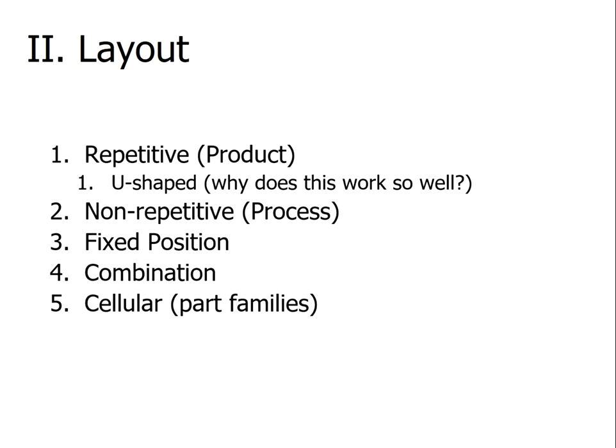Cellular, I threw in there at the end, and I actually got to see a cellular manufacturing cell at one point. Very interesting, because what they had done is installed a small version of each of the pieces of equipment in almost a cubicle or a small booth where a single operator would deburr, grind, polish, apply the finish, and package a cast gear. And the benefit of that is it's very efficient, because they load it in the machine, it starts running, load it in the next machine, and so it's just a constant flow.